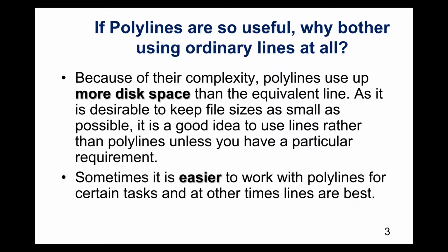So if polylines are so useful, why bother using ordinary lines at all? Because of their complexity, polylines use up more disk space than the equivalent line, as it is more desirable to keep file sizes as small as possible. It is a good idea to use lines rather than polylines unless you have a particular requirement. Sometimes it is easier to work with polylines for certain tasks, and at other times, lines are best.